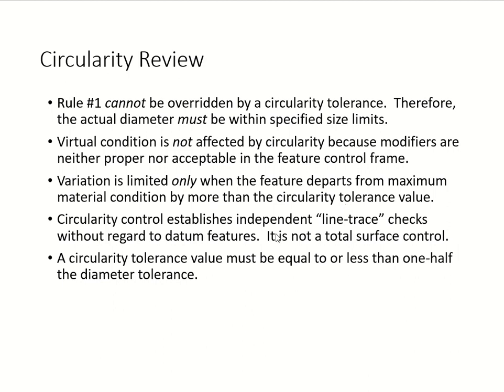Circularity control establishes independent line trace checks without regard to datum features. We don't have the datum feature in the control frame, so it's not total surface control. Again, the circularity tolerance value must be equal to or less than half the diameter tolerance. Okay? All right.